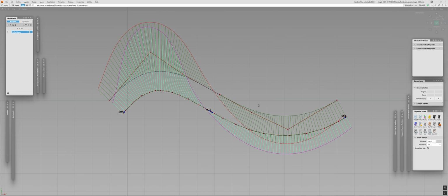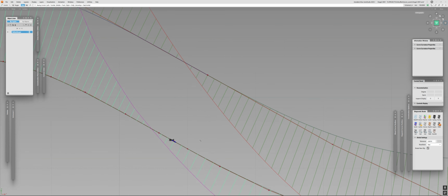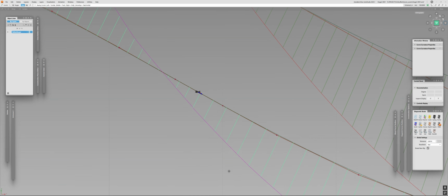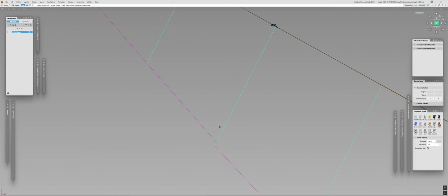But this is not the only issue, of course, because if I zoom in, let me just zoom in and zoom in. Okay, here it is. Now you're going to see that we have not only the issue with the acceleration along the curve, but the connection as well. So we actually lost curvature here. In other words, we have a curvature deviation.